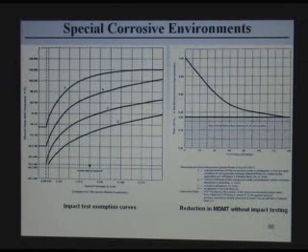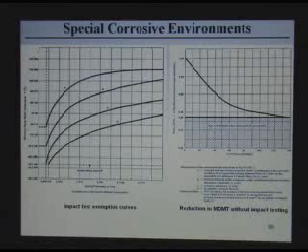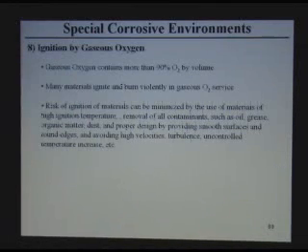You can make a curve 40 degrees parallel to this one, so you are shifting this curve down, and if your condition is here and the new curve is like that, you don't have to impact test. This is only for applications where you have low stress values, but this can happen for nozzle components, while for pressure vessels sometimes this doesn't work.